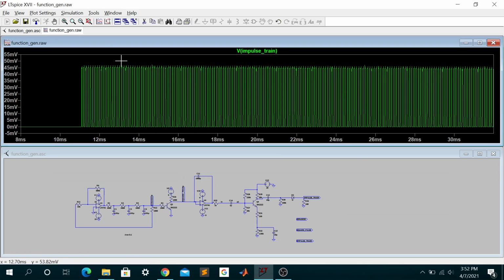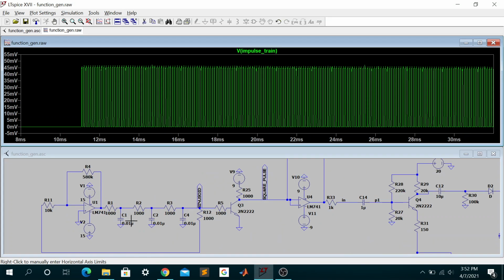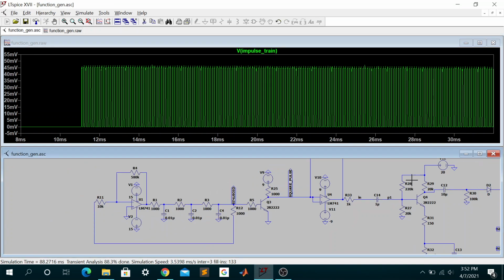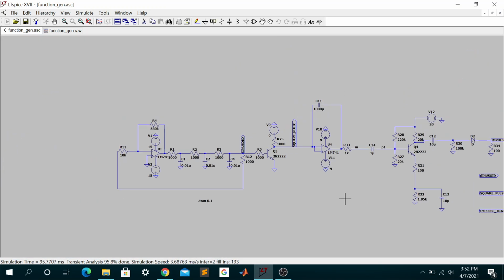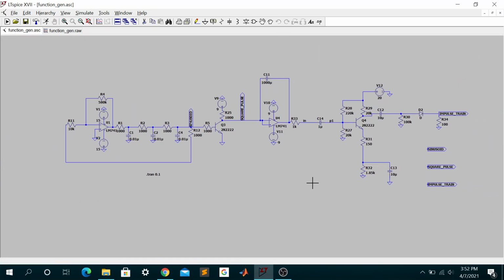You can use it for a variety of purposes like sampling a signal at various time instances. You can also tune the frequency in one of these capacitors to change the overall frequency of the circuit. This implementation is different from the other implementations because of the lower number of op-amps used in this model. Other implementations use anywhere between 3 and 4 op-amps. So this has been done using 2 op-amps and 2 transistors, which means that it uses considerably less power.